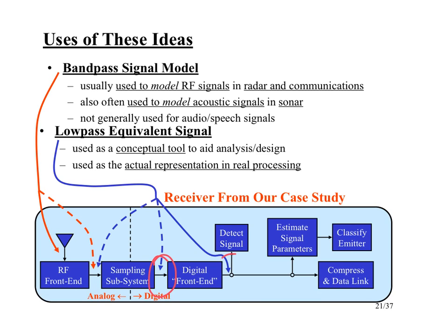We might delay the computation of it until over at this point. But at some point, either in the sampling subsystem or in our digital front end, the digital front end would compute the IQ components using something like that Analog Devices chip that we just saw. At some point in this stream, we literally get samples of the I component and the Q component, and that's what we actually do our processing on.